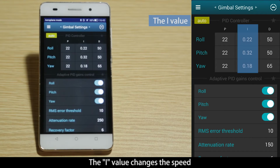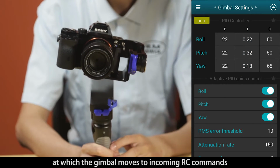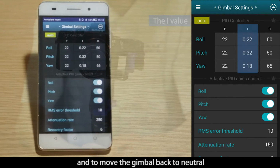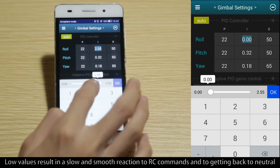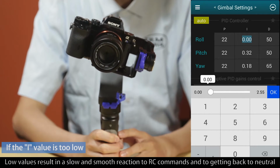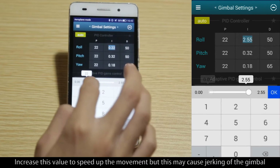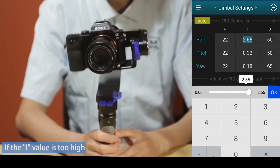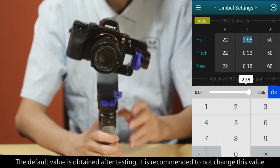The I value changes the speed at which the gimbal moves to incoming RC commands, and to move the gimbal back to neutral. Low values result in a slow and smooth reaction to RC commands and to getting back to neutral. Increase this value to speed up the movement, but this may cause jerking of the gimbal. The default value is obtained after testing. It is recommended to not change this value.